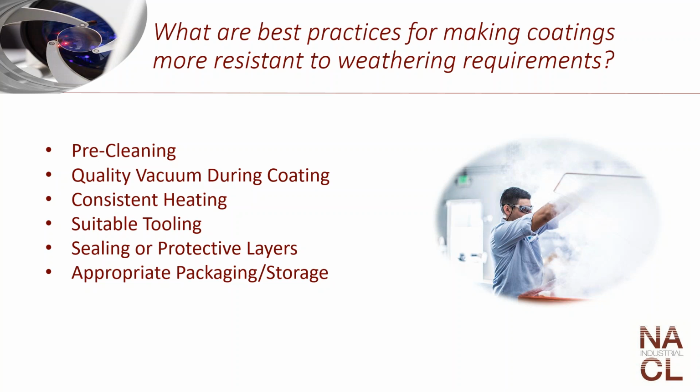So it's important to know not only where your coated optic is going to be stored, and some of the environmental parameters there with heat and humidity, but also what kind of packaging you want to use. And if you're reusing packaging, how often should you clean it? How often should you throw it out and start with new packaging? It's one of the last things everybody thinks of, because there's so much complex engineering that goes on ahead of packaging and shipping an optic, but it's vitally important to make your optic stand up when there's a rugged environment that it needs to survive.